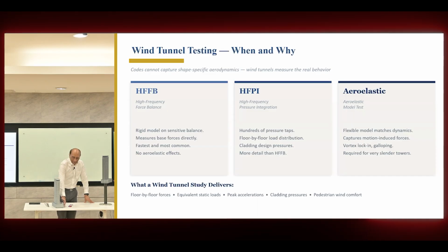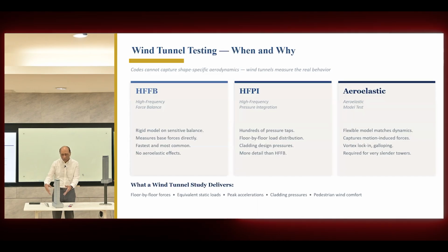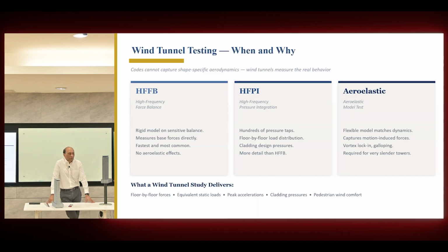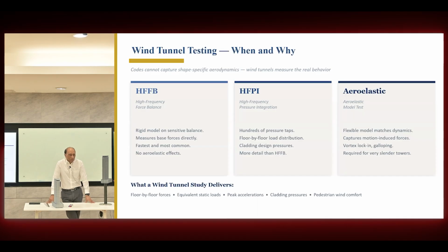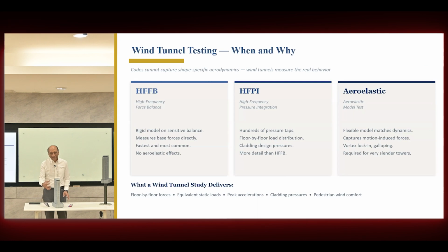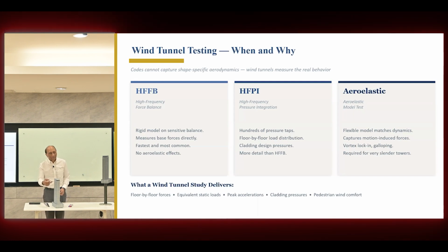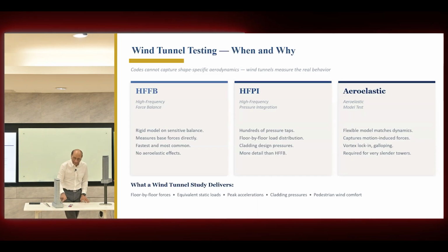So we need to measure the pressure close to the ground and on the top of the building. And this is not alone. All the buildings around the building also need to be modeled, so we can follow the wind pressure, build-up, suction and all of that. This is used for design of the cladding, because the glass should be designed locally for each pressure. So the pressure at each location will be used to design the cladding and the glass. And this will be used to design for pedestrian comfort and pedestrian flow.